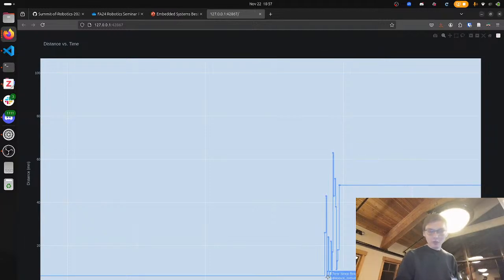So here we can see that we get anywhere from 63 millimeters right away, farther than what it initially measured, so probably bounced back and forth, as well as low as, where did it go down to, 6 millimeters, which is probably not even within the range of what the sensor is capable of. It's probably not even able to read out that close, but it thinks it did, just because of the noise of the system here. Very noisy, as you can see.